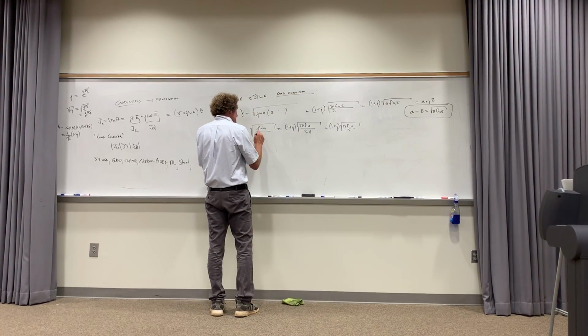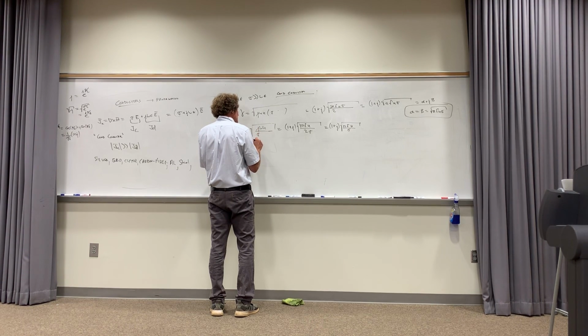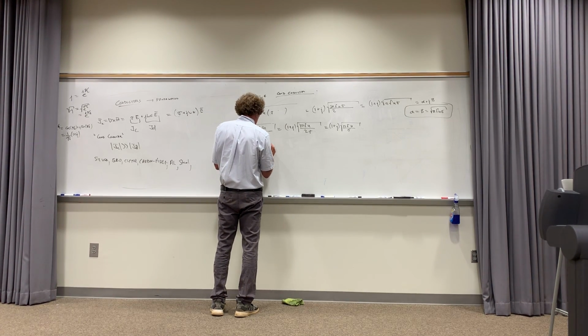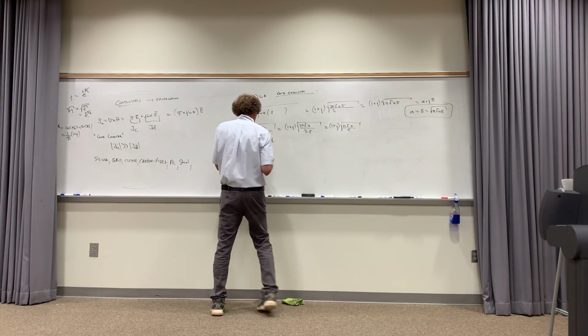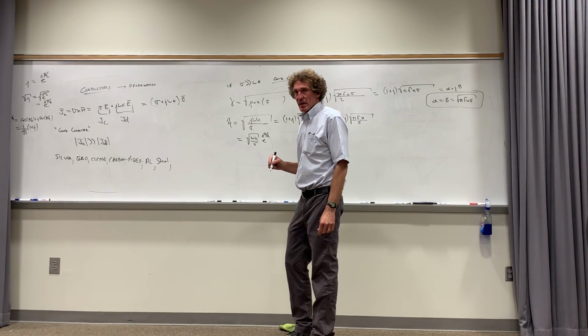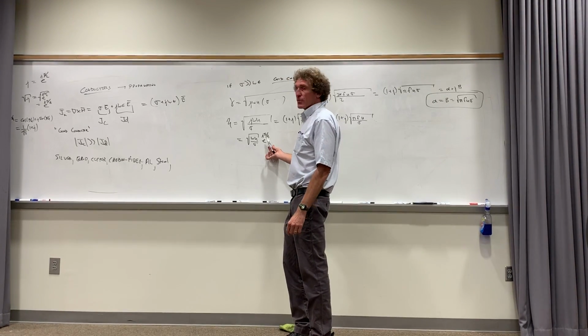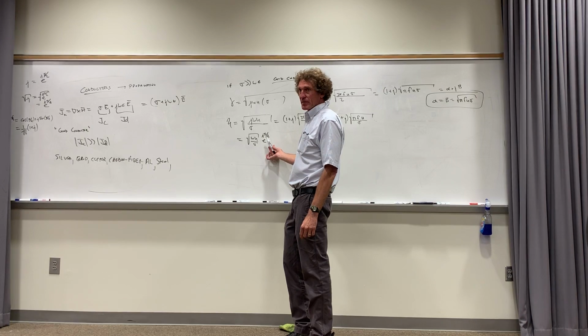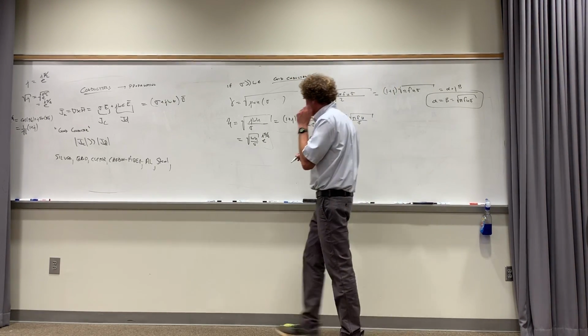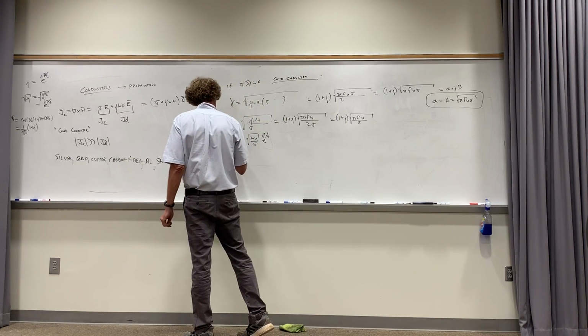Another way to write this is simply, when I have the square root of j, I know it's going to be at 45 degrees, so I can say it's the square root of omega mu over sigma, and I can just put right here e to the j pi over 4 outside, and I can leave it like that. You follow me? And that is at an angle of 45 degrees. Follow me? So this is going to be the polar form. This is the rectangular form of the intrinsic impedance. And keep this one in mind. We use this a lot.